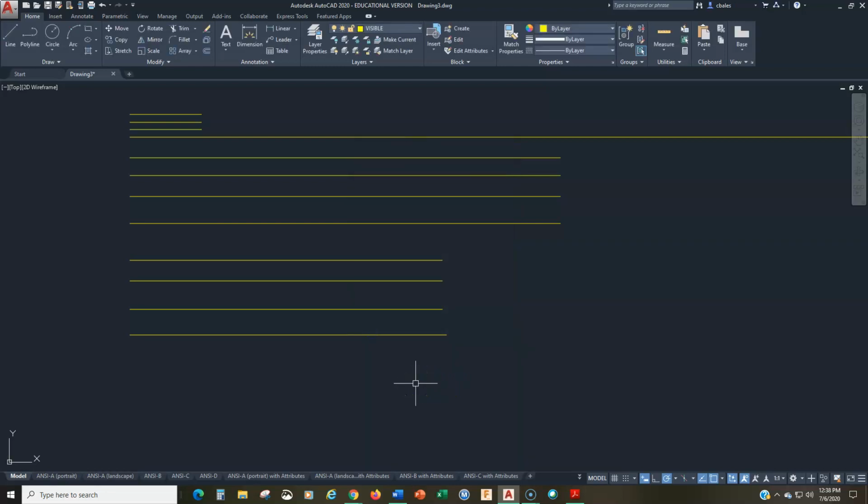Okay, so that is the units command in AutoCAD. It's required when you're doing a feet and inches drawing, such as an architectural drawing. And those are the different ways that you can enter the values, okay? You always need the apostrophe to identify the feet. And then the inches, you don't need the double quotes. And you separate the fractions from the inch with a dash, okay?